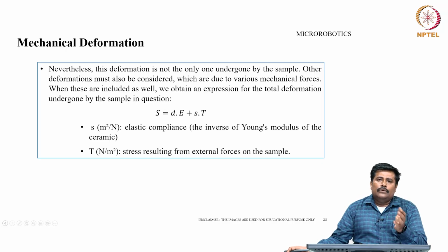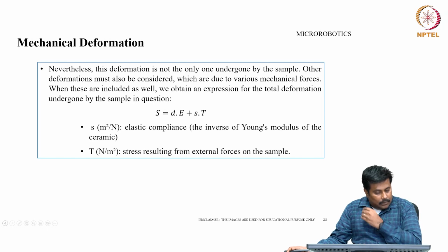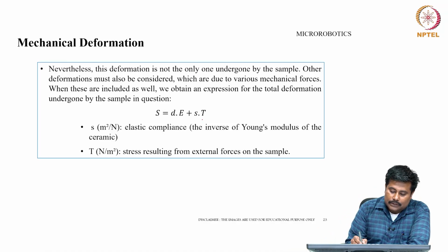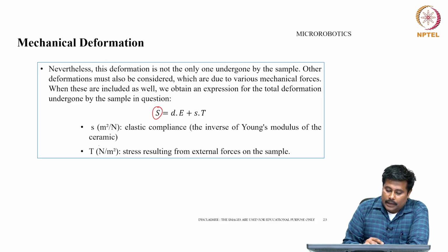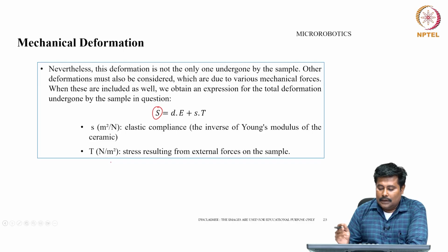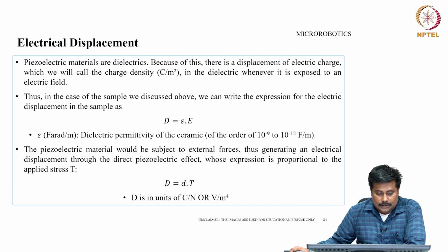When these are induced as well, we obtain an expression for the total deformation undergone by the sample in question: S equals d dot E plus s dot T. Here capital S corresponds to the total deformation, small s is the elastic compliance, the inverse of Young's modulus of the ceramic, and capital T is the stress resulting from an external force on the sample.